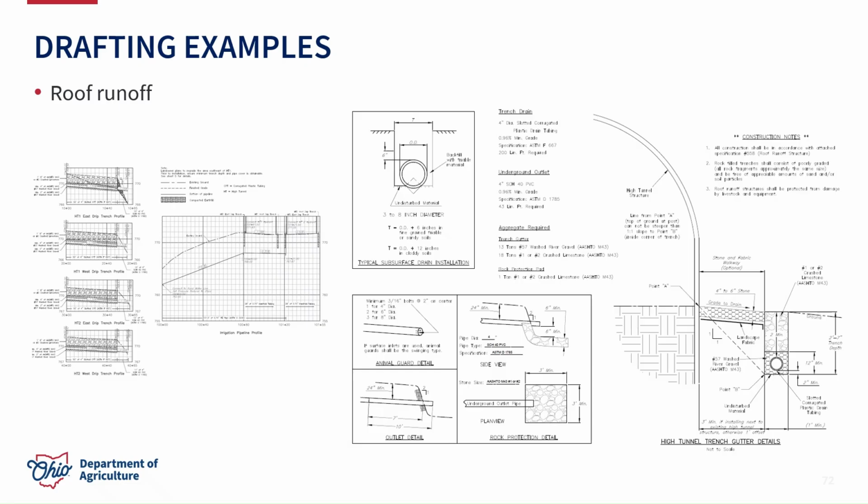Looking into some associated practices, we talked about that rock trench being off of a high tunnel, so this is the standard detail page for that, showing the installation of the rock trench, some of the stone requirements and the sizing, installation of that subsurface drain, and then our underground outlet protection. And we'll want to make sure we have any profiles for that to make sure our pipes are put on the proper grade to have capacity.